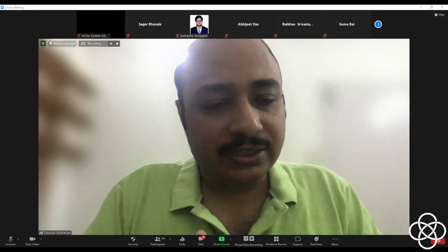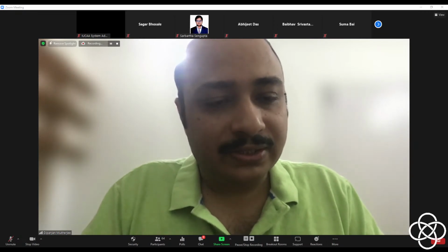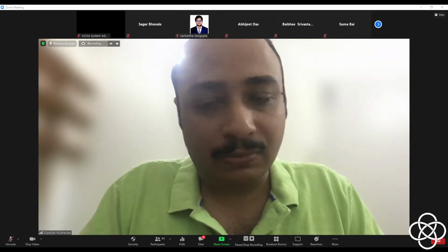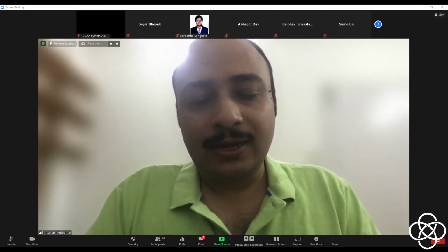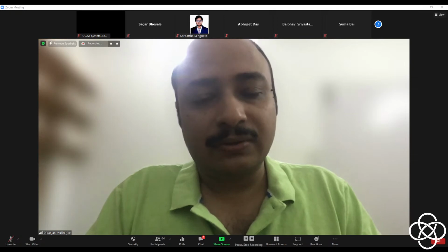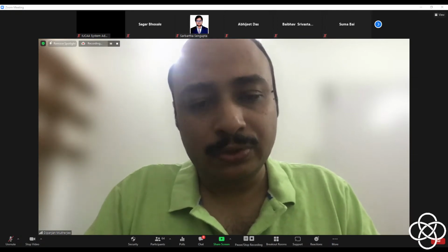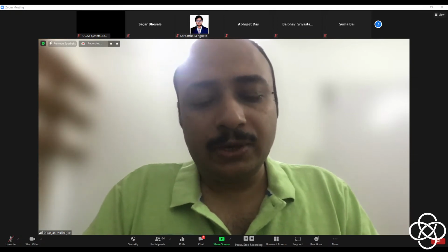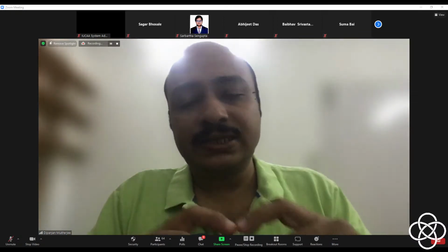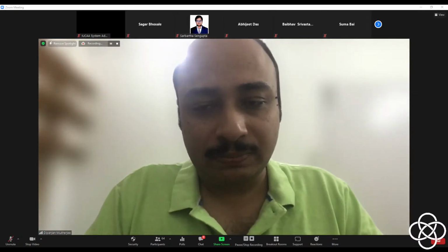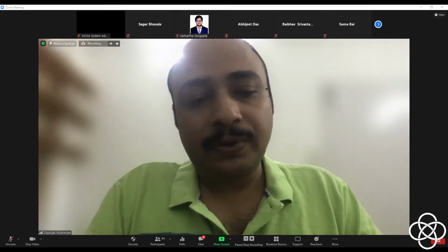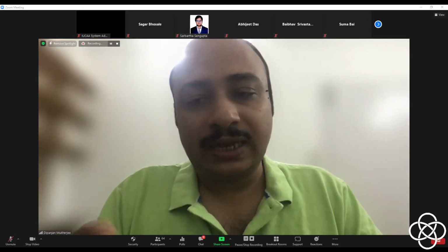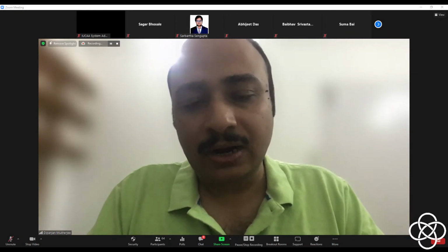But the question in the chat, I think it's also important to address. So I'll just address this anyway. It's how to test the accuracy of the model. It's a very important question, and this is something that we spend a lot of time thinking about when we are developing a new numerical module. So what we usually do is we try to set up a very simple analytical problem first, which has an analytical solution. And then we compare our numerical results with the analytical results and see how far off we are.